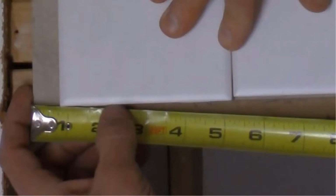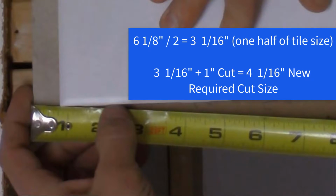However, if the cut size was 1 inch, which is less than half of a tile, add 1/2 of the tile unit size, 6 1/8 of an inch divided by 2, or 3 1/16 of an inch, to the 1-inch cut, which equals 4 1/16 of an inch. This would be the cut size on the left and the right.